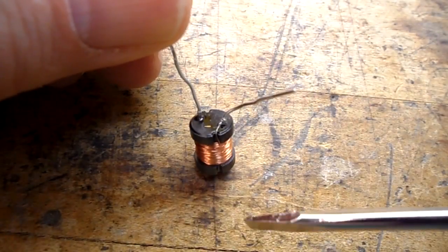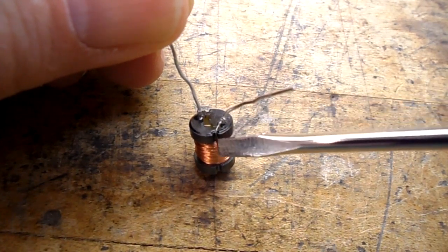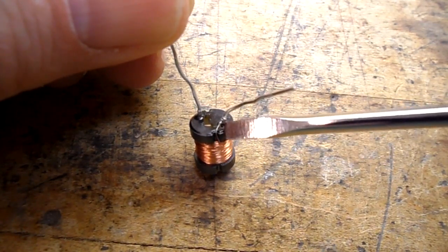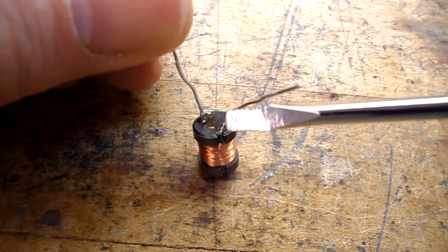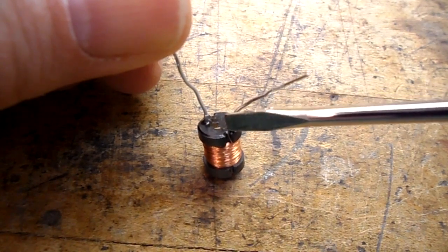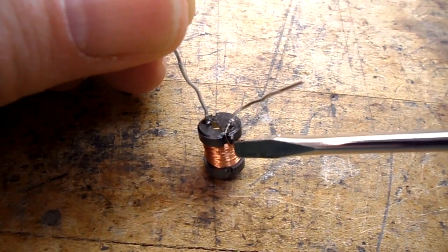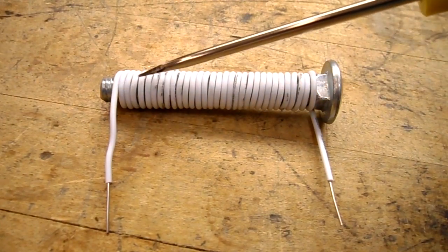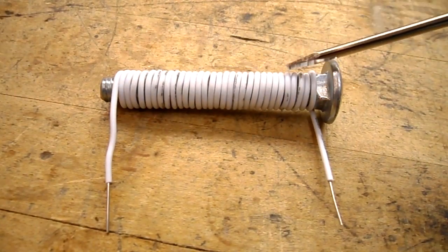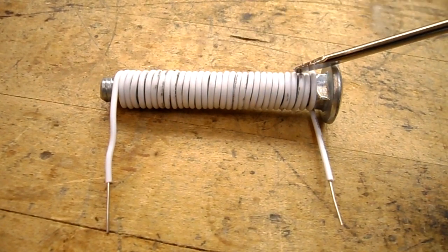I just wanted to show you that these thin wires are connected to the legs of your inductor. So they're very thin wires. They're just wrapped around the leg and then soldered in place. So if you spread the legs of these inductors too much, you will break these tiny wires, and they'll no longer be inductors. They'll actually be open circuits. You can also make an inductor by taking your standard hookup wire and wrapping it around something like a bolt or a nail, and this will create an inductor.